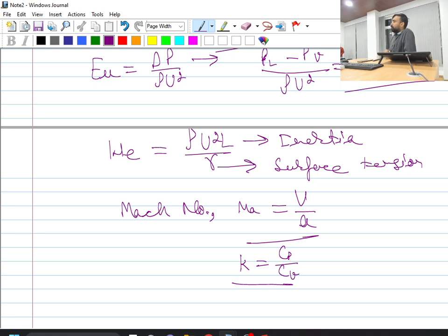So what I have done here is list a set of dimensionless parameters, a few of which came from non-dimensionalization of the basic governing equations, and a few I have written in addition, because when I non-dimensionalized the governing equations I only considered incompressible flow. But if I use compressible flow, then I can have involvement of the speed of sound and the ratio of specific heats as well.